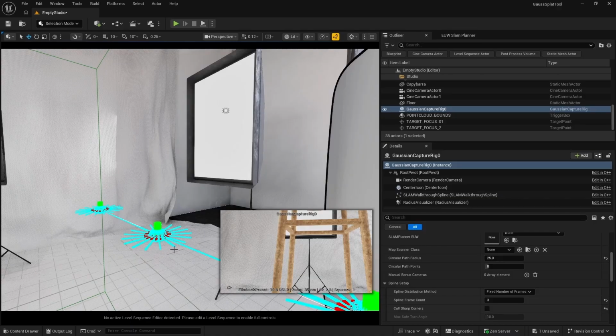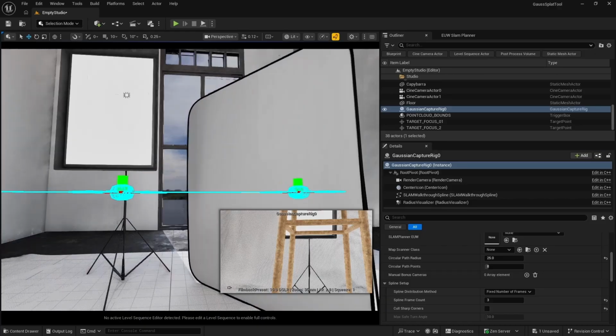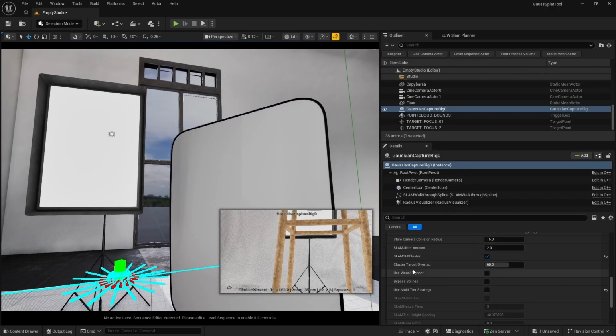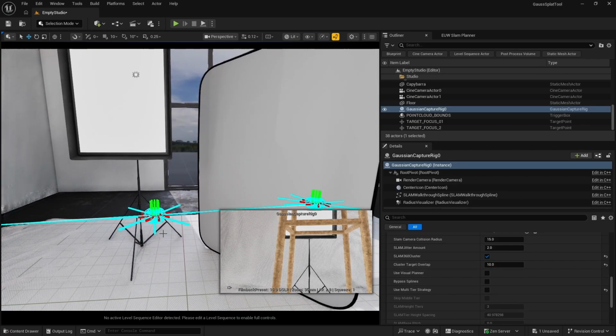At each camera node, you take maybe 8 images that cover the whole 360 view. Let me go through this. You see now my cluster overlap is at 60%. Maybe I want an overlap of like 20. So if I have 10, you see I have very few cameras to cover that overlap, because imagine the lens is wide.